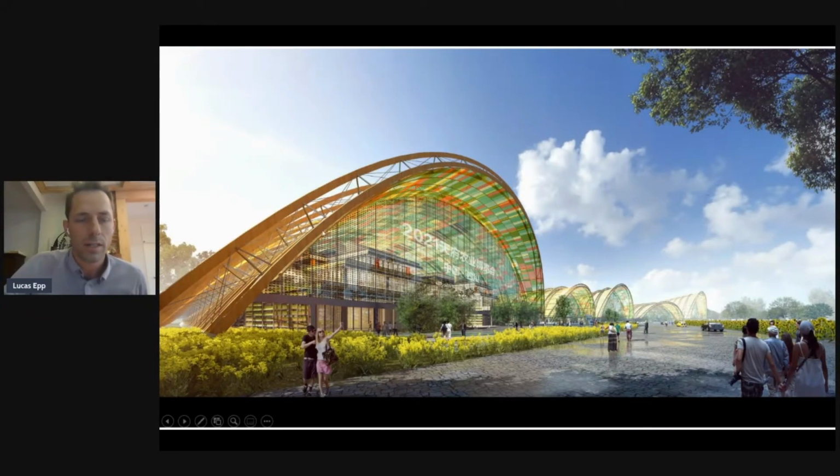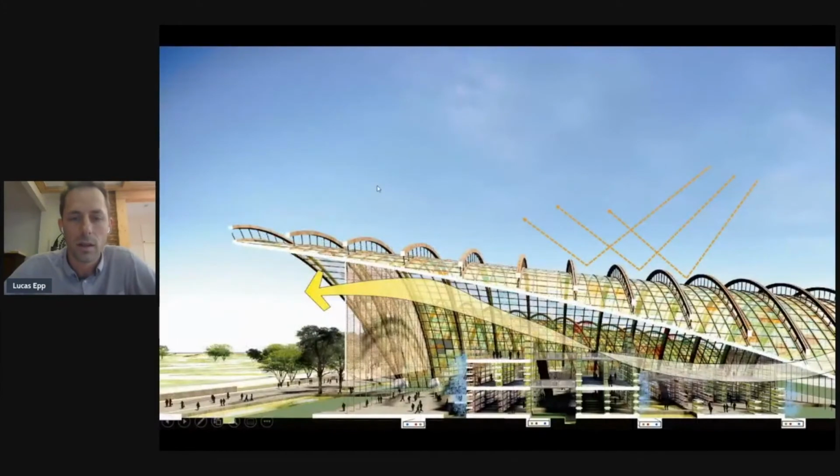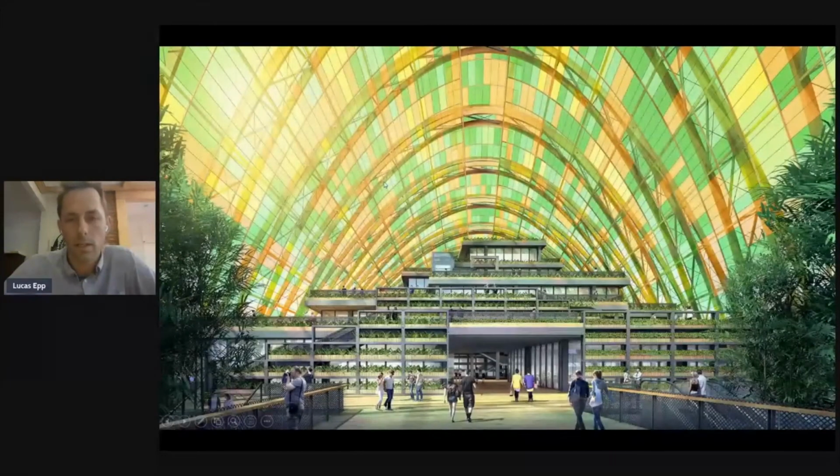And the challenge the architect out of Beijing posed to us, as we were involved in the concept development for the structure 2-3 years ago, was: can we find a way to expose the glulam on the outside of these vaults so that people can actually see the wood? That's a real challenge from a durability perspective. Can you really expose the wood? The architectural concept was keeping the cladding on the inside. We ended up cladding the bottom chords of these trusses, but the top chords are exposed, which is a really neat architectural statement as you walk up to these giant vaults.